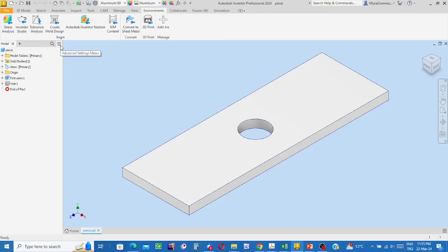Well, if we know that the material will be in the elastic region and yielding will not occur, since it is easier to use, the classical stress analysis tool of Inventor is recommended. Not Nastran. Nastran is more powerful, but for simple analysis it is too complex.